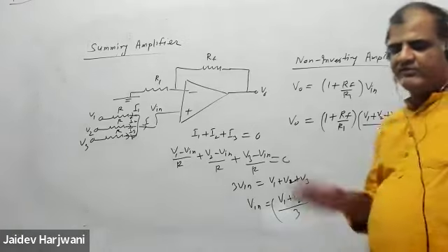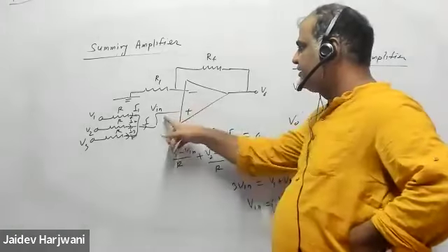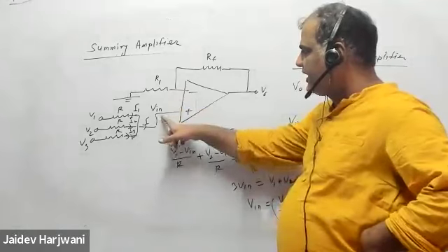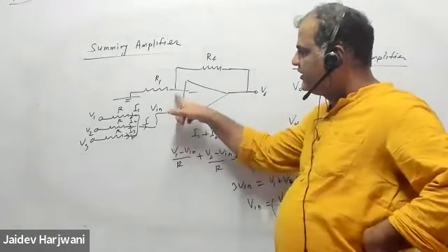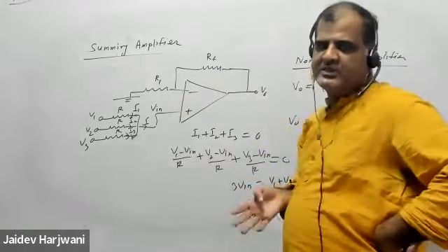So op-amp questions are very simple. You only have to remember some properties. If it's ideal, these two points are the same. And second, no current is going into the inverting terminal. That you have to remember. You should also know some superposition principle or nodal analysis.